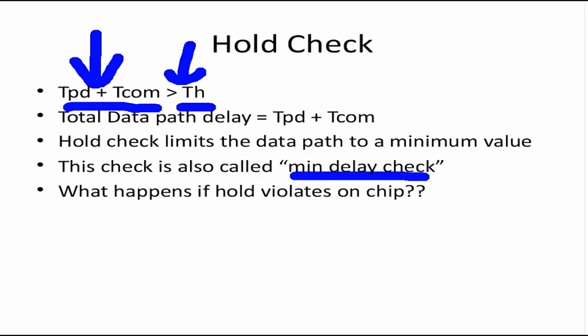There can be a setup violation. You can manufacture a chip with a small setup violation, but not with a hold violation. You have to make sure that all the hold timing constraints are met. Again, we will try to map this equation to the corner based STA.